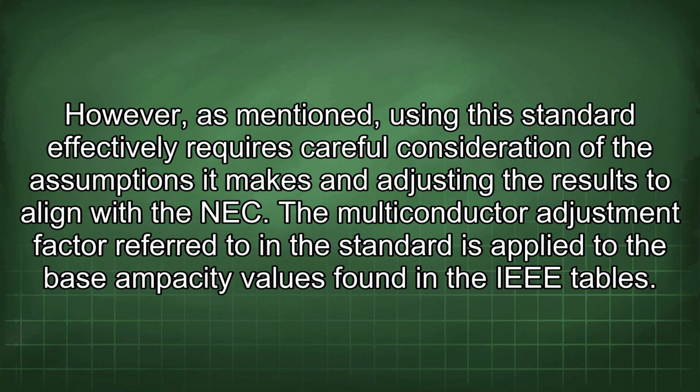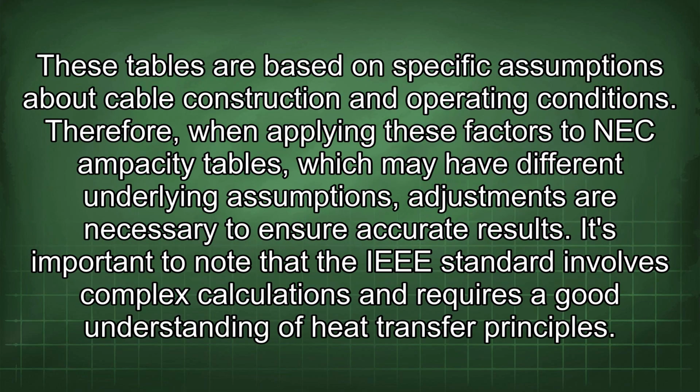However, as mentioned, using this standard effectively requires careful consideration of the assumptions it makes and adjusting the results to align with the NEC. The multi-conductor adjustment factor referred to in the standard is applied to the base ampacity values found in the IEEE tables. These tables are based on specific assumptions about cable construction and operating conditions.